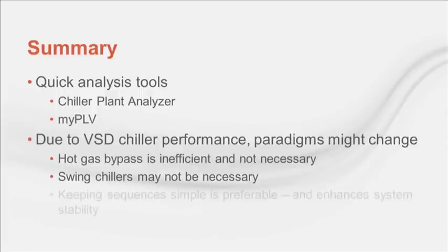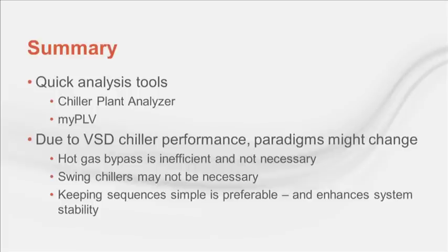And finally, when systems are designed, installed, and commissioned, we want them to keep operating stably and efficiently. Simple is good. There are times when we can make the system so complicated that the operators will take control in hand. So many times, complicated sequences that are not well documented or understood aren't used, and the result is more real energy use than efficient, simple sequences.